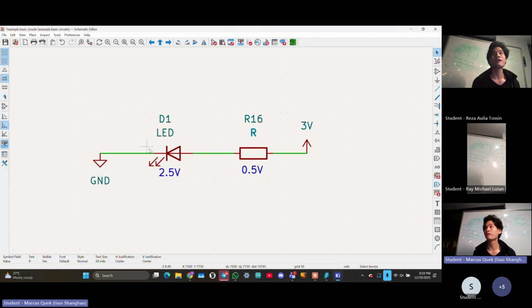Then after that, you have to check what is the current through the LED. What do we do if the current is too high? We just increase the resistance, right? No choice. And then the voltage drop will be greater. Then we're not running it at max voltage? The voltage across the LED is assumed to be fixed. Oh, right, because it's a diode. It does not have a flat curve. Yeah. Okay, diodes are magic.